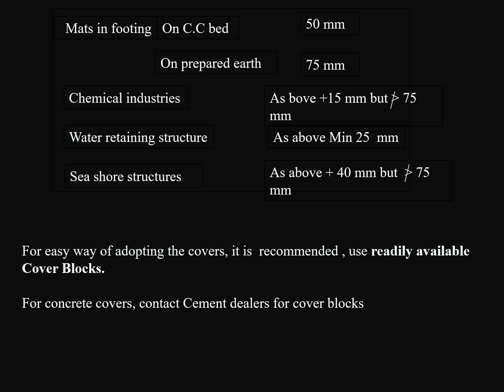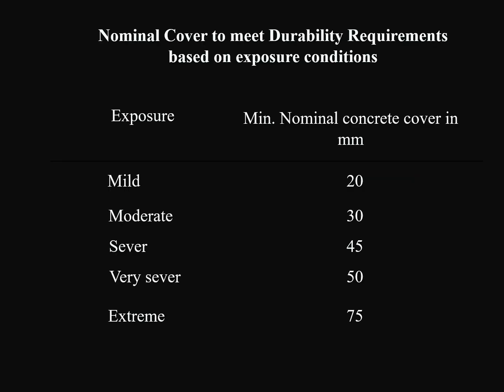For easy way of adopting the covers, it is recommended to use readily available cover blocks. For concrete cover blocks, contact cement dealers. Nominal cover to meet durability requirements based on exposure conditions. For mild exposure, minimum 20 mm, moderate 30 mm, severe 45 mm, very severe 50 mm, extreme 75 mm, in no case more than 75 mm.